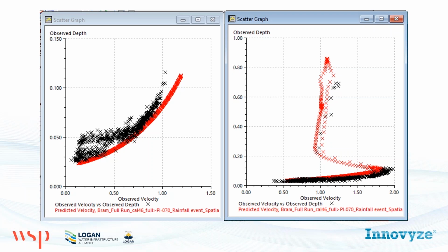ADS are a company that do flow monitoring, and the company that we actually prefer to use most of the time. They have an excellent poster, which you can download from their website, I believe, which describes the different types of scatter plots and what they mean. I'm just going to go through a couple of things here that are pretty useful. The first scatter plot on the left is basically showing typical in-pipe performance. There's a slightly exponential relationship between depth and flow. There's nothing particularly unusual happening there. That could be described with probably the Manning's formula.